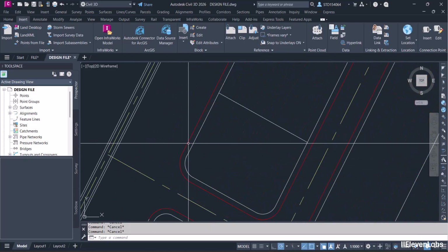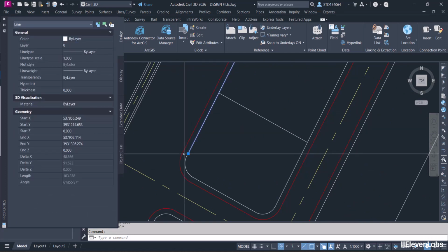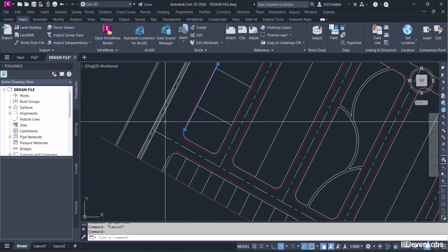Obviously here when I say Ctrl+1, I find that this line is on layer 0, and here it's the same. This line is on layer 0. So I should organize all my lines and convert all the lines from line to polyline. I shouldn't have arc or line first.